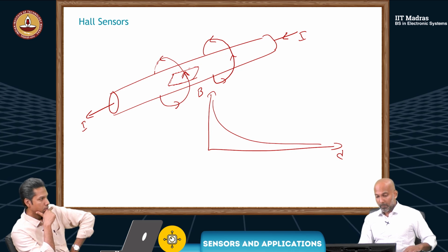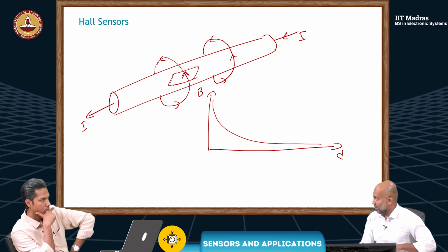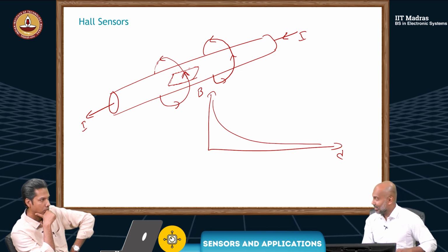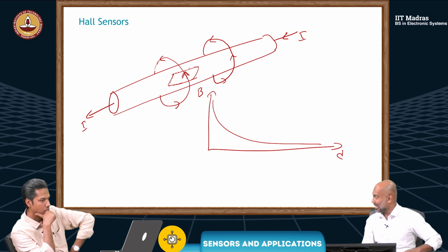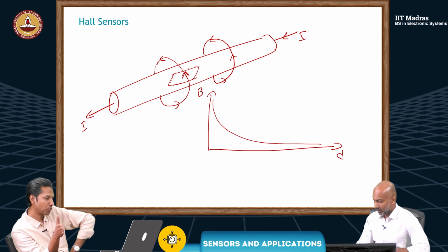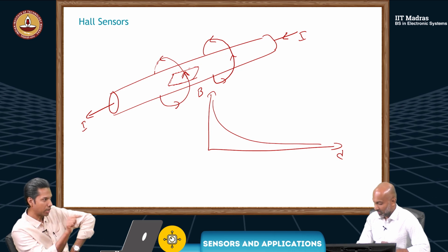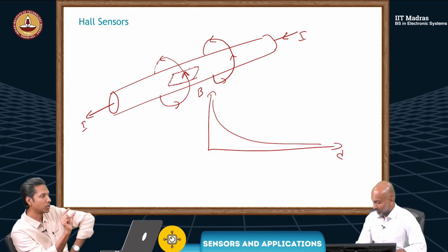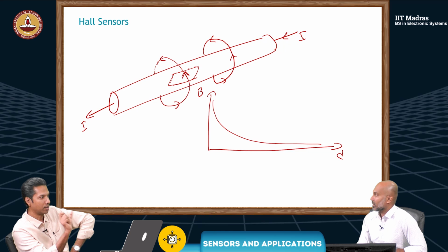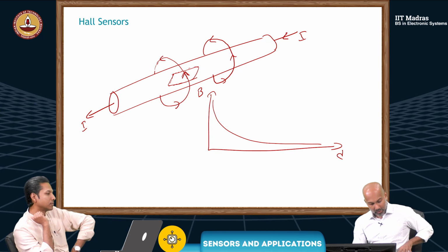So in fact, you can technically use this approach. But the amount of magnetic field intensity that you can measure is probably not a lot. It depends on the amount of current flowing through the conductor, and also the distance from the IC to the conductor. And then we also need to ensure that the gap between the conductor and IC is maintained, because this calculation goes as per that. Exactly. So what's the strategy here then?